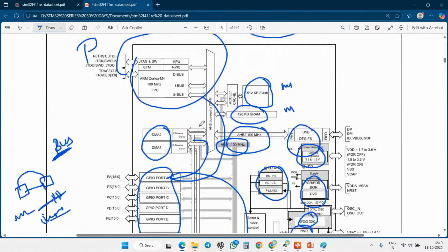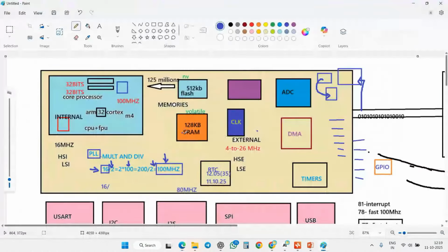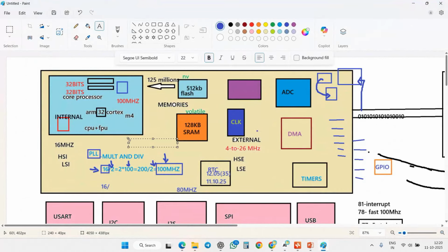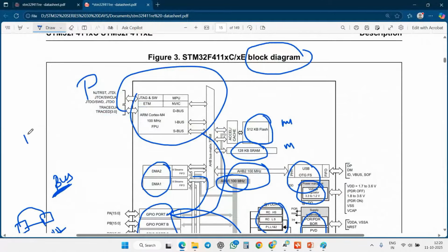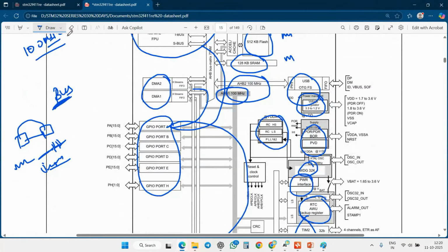Okay. Here they have been using the buses, and these buses have two variants. I'm going to write this concept here. It is called an AHB and another one is called an APB. What is the purpose of AHB? If you want to configure the high speed buses, which are going to transfer at around 100 megahertz, you can connect that. You just use this AHB bus.